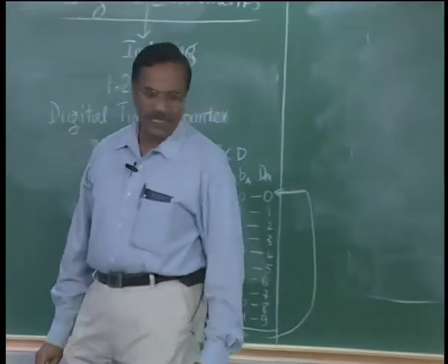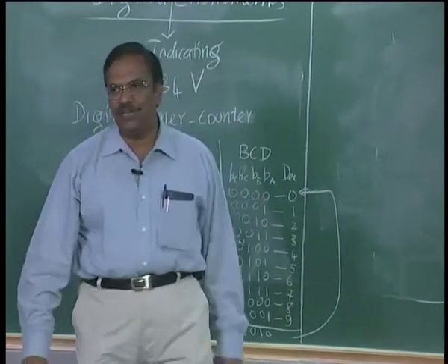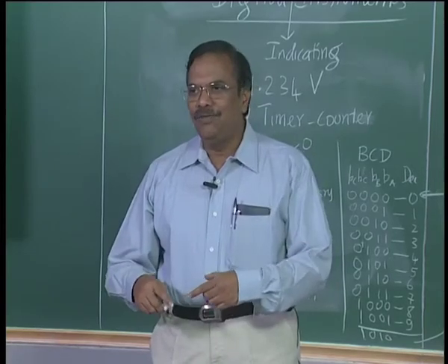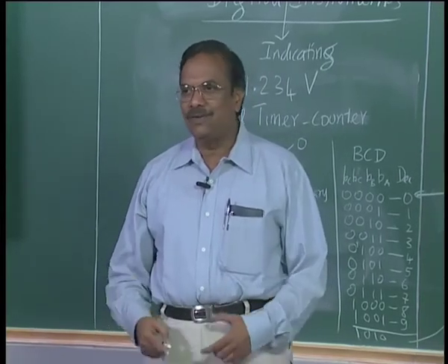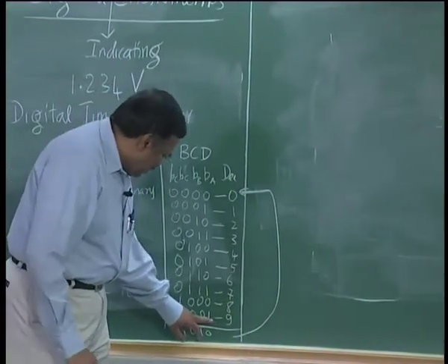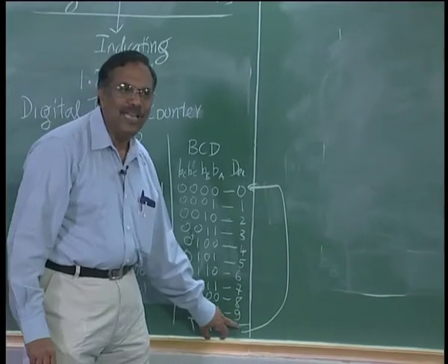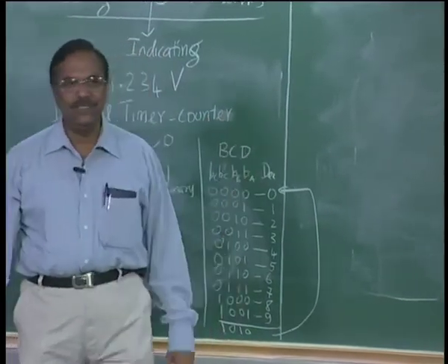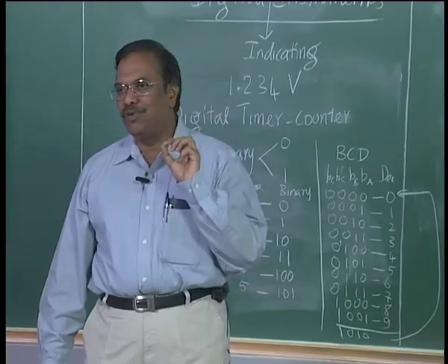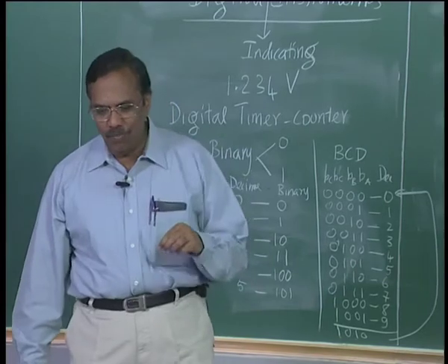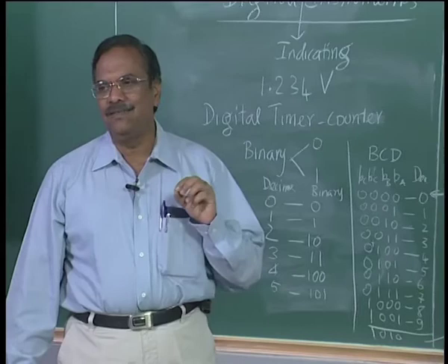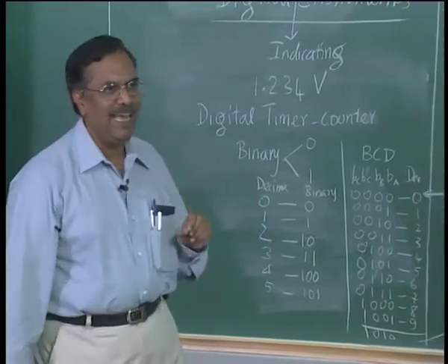The carry output is the AND gate output that tells me that there is a rollover from 1001 to 1010, because in binary coded decimal, the 9 must be sensed, and when you go to 10 you should reset it to 0000. So, that signal which forces the output to go to 0 at the transition from 9 to 10 is called the carry, right.